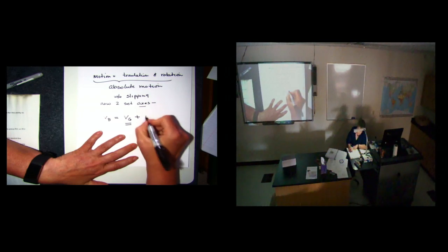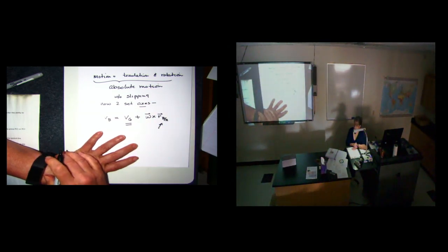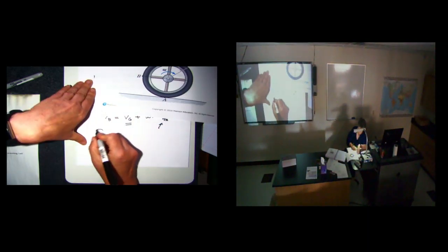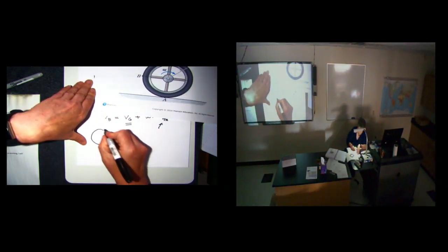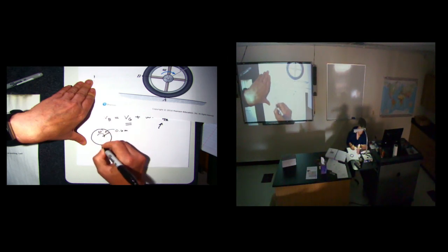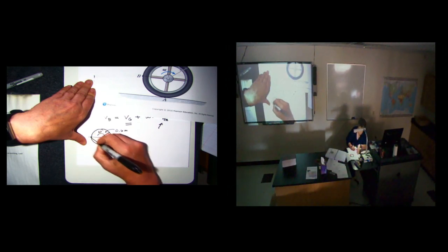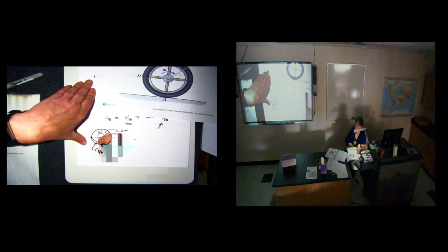But if I want that in vector form, remember I'm going to use my right-hand rule, and in this case, because I'm going in the wrong direction, this would actually be written as minus 10 in the k direction. So everybody with me, where I get my directions all in place? Why would you put it as k? Right-hand rule, rotational motion. Remember, my rotational motion is going to have right-hand rule. I'm going into the board. If I'm calling this x and y, I'm going into the board and it's k, which is why it's negative.